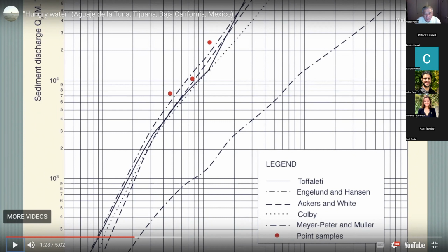And over here is from 13 to 24. So that's almost double. That's 100%. So you can see, now why does this happen? It happens because you can see both ordinate and abscissa are log cycles or log scales. The variability is tremendous. So that is the reason why you cannot pin down readily the amount of sediment transport. And we got to accept the best of practice, which is what I am telling you right now.